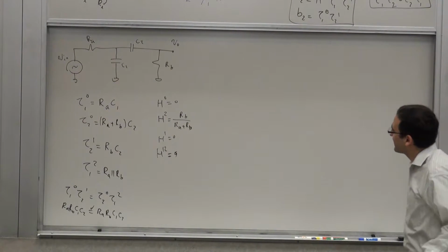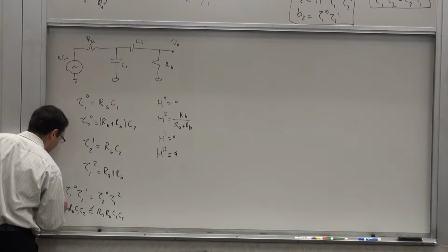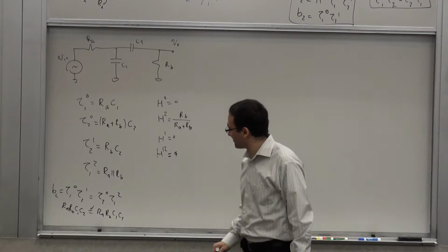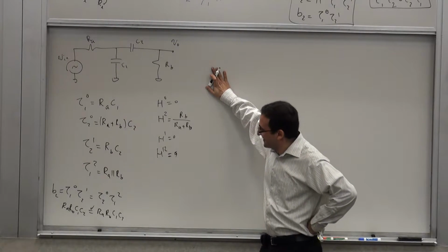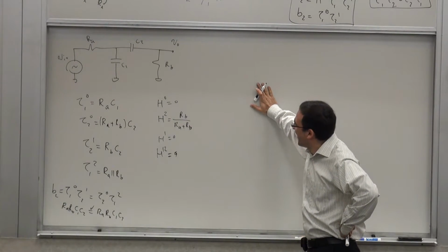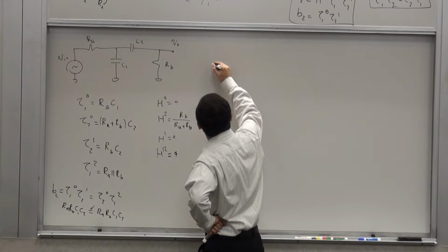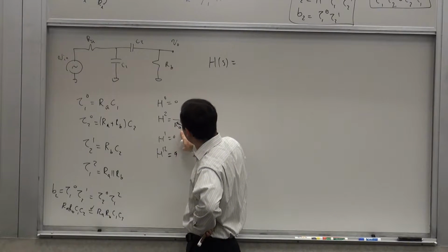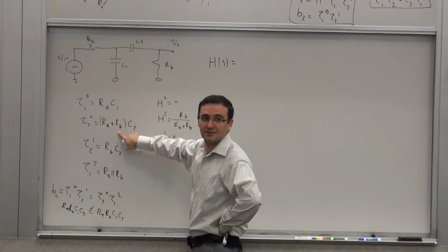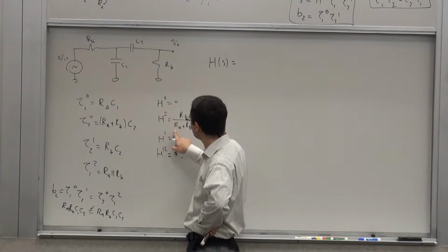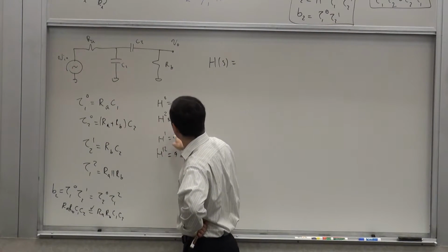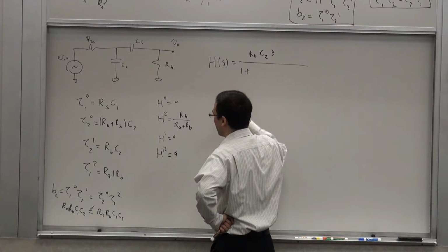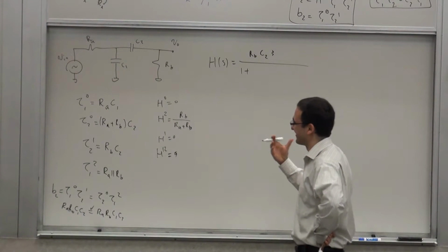Okay, alright, so that's what we have. And by the way, this happens to be our V2. So we killed two birds with one stone. Okay, so what we have here, the transfer function looks like this. H0 is 0, so the only term we have is this times that, times S. A1 is the only non-zero term, because this is the only non-zero H. This times that is easy because this cancels that, so I'm left with RB C2 S divided by...